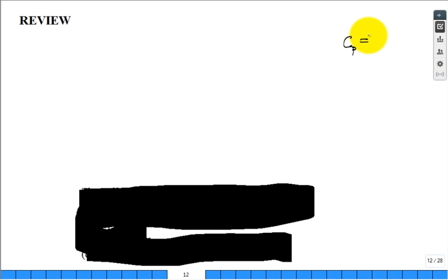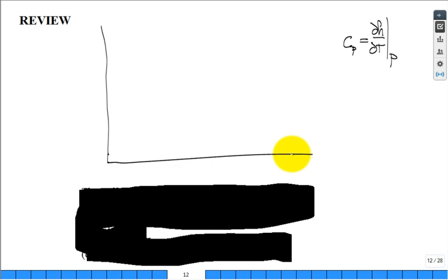Yeah. And so it's the rate of change of enthalpy with respect to temperature holding pressure constant. So why don't we do this? Why don't we take the same data, turn it around, and do temperature on the x-axis, and we'll do enthalpy on the y-axis, because what is the slope of that curve? dH/dT is C, specific heat. So it's the same data, it's just plotted a little differently.